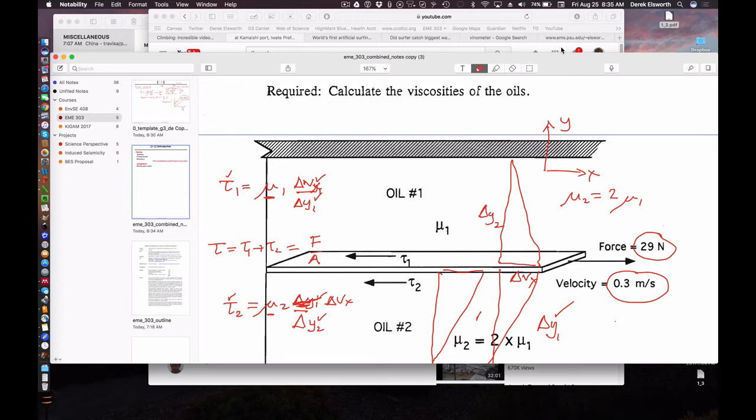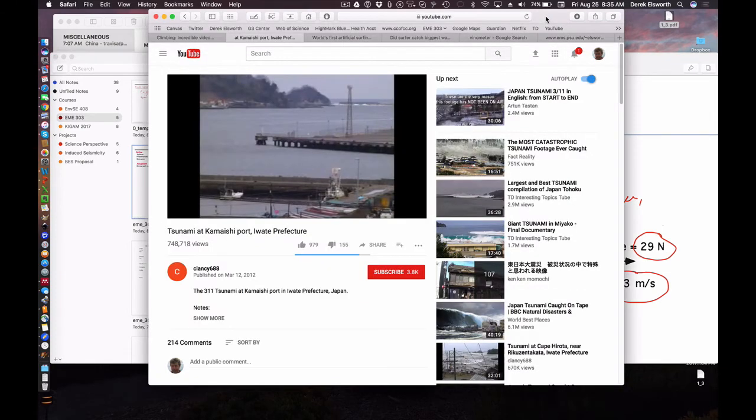A question: if fluid can't carry a shear force, how does a shear force affect the velocity throughout the fluid? Good question. It can carry shear force, but that shear force is so small compared to the compressional force that it's negligible. The shear modulus G, which we looked at in those acoustic velocity plots, is tiny. It's almost 0. Small but finite, and it's actually related to viscosity. Great question.